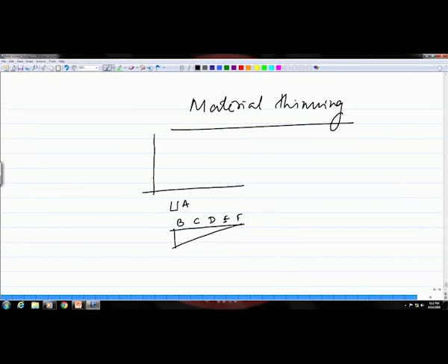As the thickness decreases, you would see that... so, this is A and this is B. So, that is the first point where you have full thickness, and as you move the probe to other points C, D, E, F, where the thickness is less, then you will see the lift off curve is changing like this and so on. Okay, so, if you connect all these points, and finally, when you come to F, this will go back to the initial position, because there you have almost nothing.